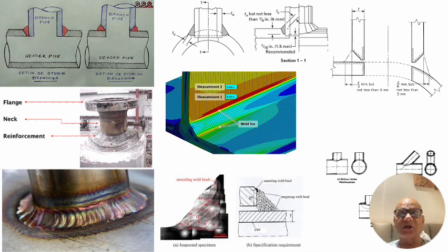And then physically we will have to correct it. If you try to correct that physically without welding, this highly stressed point which is seen here, the red line on the top of the fillet, is the one which is likely to crack.